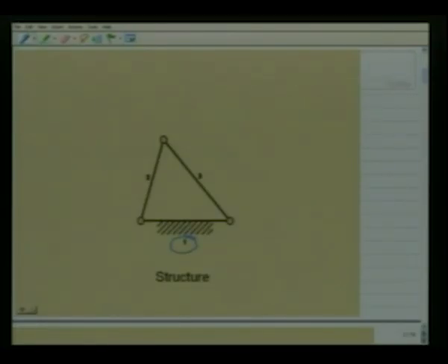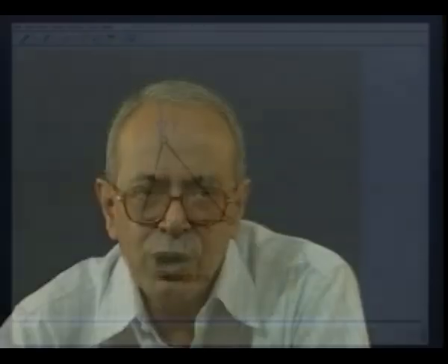In fact, if we apply an external load, there is no relative movement between the various links. This load can be supported by this assembly. Such an assembly with 0 degrees of freedom is called a structure. Hence, we see that the four-link planar mechanism is the simplest mechanism that we can think of.